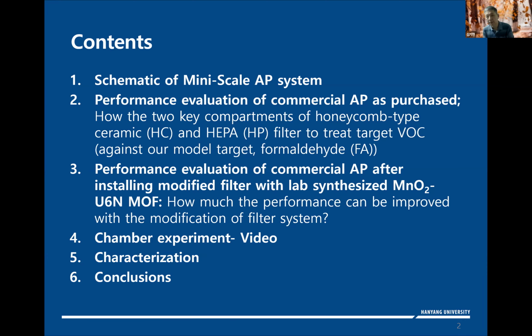After modifying the air purifier, we run the same test to treat formaldehyde and estimate performance metrics like breakthrough volume and reaction kinetics, and we make a comparison between the system as purchased versus the system after we modified. Then I will go over our chamber experimental video briefly, then characterization, and finally the conclusions.